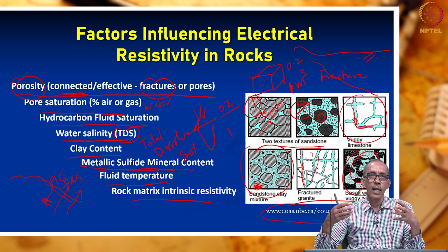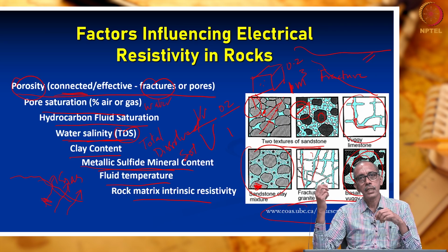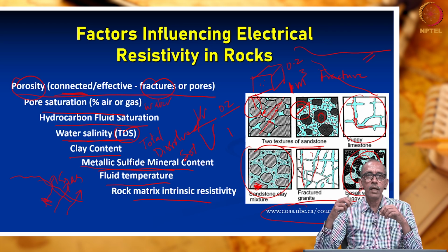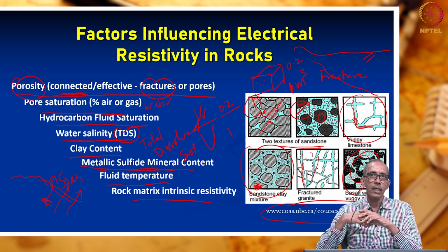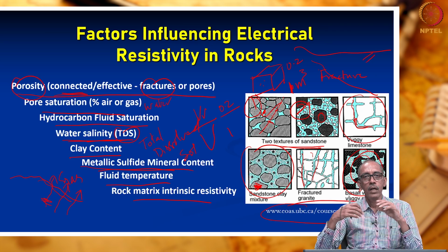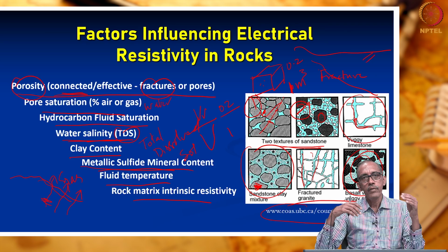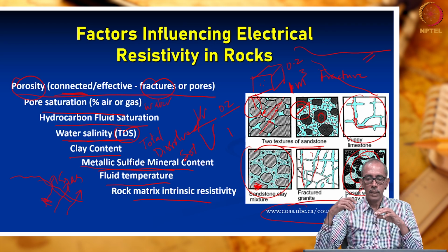The resistivity measured in basaltic rock depends on the amount of vesicles or cavities present, and whether these vesicles or pores are filled with water or some secondary material. So all these factors control the resistivity of the rocks. So in this lecture, we have seen what electrical methods are, what the three important electrical methods are, then we had a look into resistivity methods. Thank you.